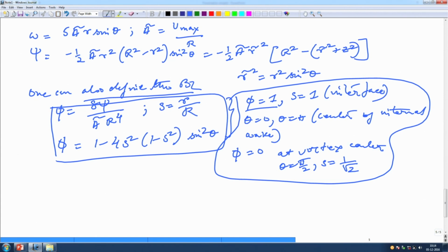Using a combination of these two, we can define what is going on inside the droplet. This solution is valid for high Reynolds number behavior. The viscous terms are obviously neglected, so it is the inviscid solution for the internal liquid flow. So, this is valid for high Re essentially. For low Re,